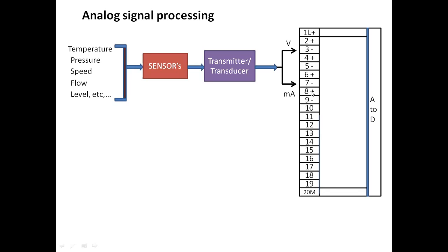Then this electrical signal, 0 to 10 volts, varies according to your sensor, right? When your sensor is sensing the data, it is increasing or decreasing, so the output of this conversion is also varying. That signal goes to your channel on that particular module, which is then converted from A to D. There is an analog to digital converter on your analog input module.